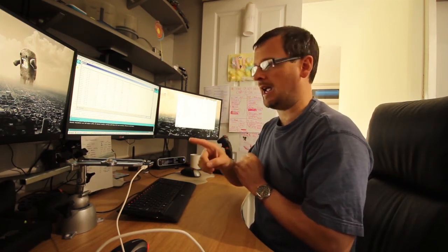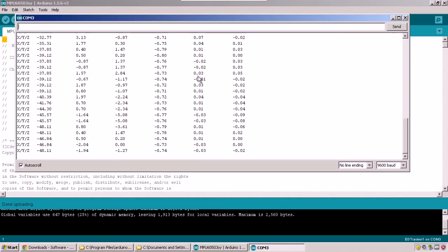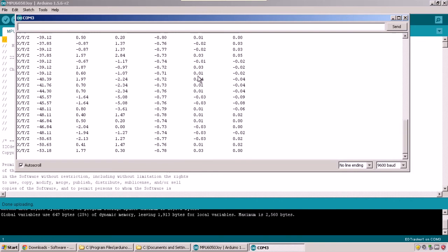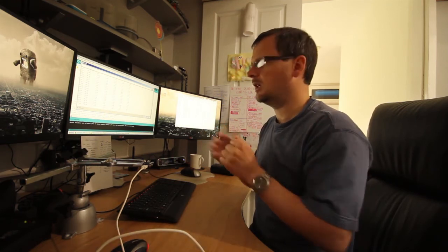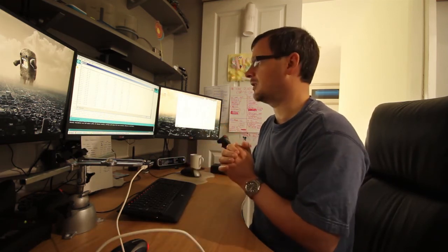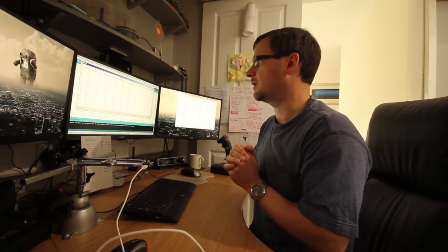What we're looking at here now is this third from last number. You can see at the moment it's 0.74, 0.76, and this is how much the x-axis is changing over time, and it's a rolling average, so the more samples we get, the more accurate it will get. It's currently calculating how much the x-axis is changing even though it's not being moved. So again, it's critical that we don't move the device, and we watch this number and give it 20 minutes to average out and figure out what it's set to. And this number will become your drift number.